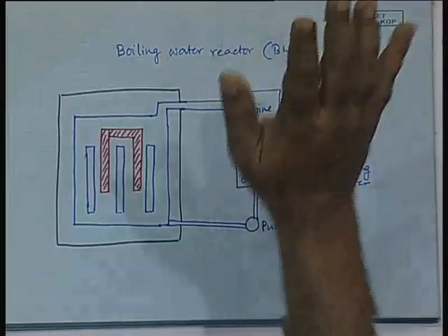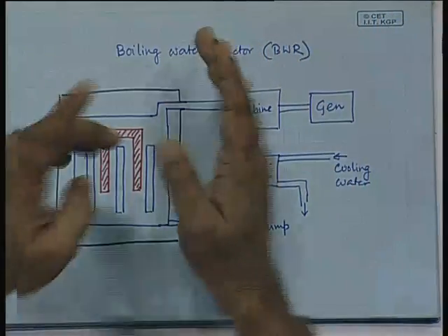So, the next stage is that within this chamber it is not allowed to boil. So, this structure will be the same chamber, water is being fed in and water is going out, but the whole thing is water. It is not allowed to boil into steam. But later after this, there will be a heat exchanger in which that pressurized water gives the heat to normal water, allowing it to boil. Clear? So, let us draw that schematic diagram.